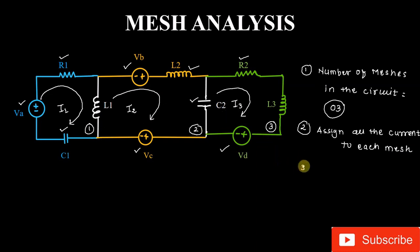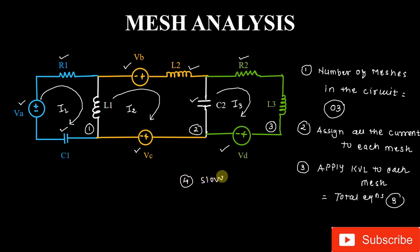Now according to the procedure, the third step is to apply KVL to each mesh. Okay, and how many KVL equations will there be? Here we have a total of 3 KVL equations, because we have 3 meshes and 3 unknowns. Once we get the KVL equations, in the fourth step we solve these 3 equations, and we will get the values of I1, I2 and I3.